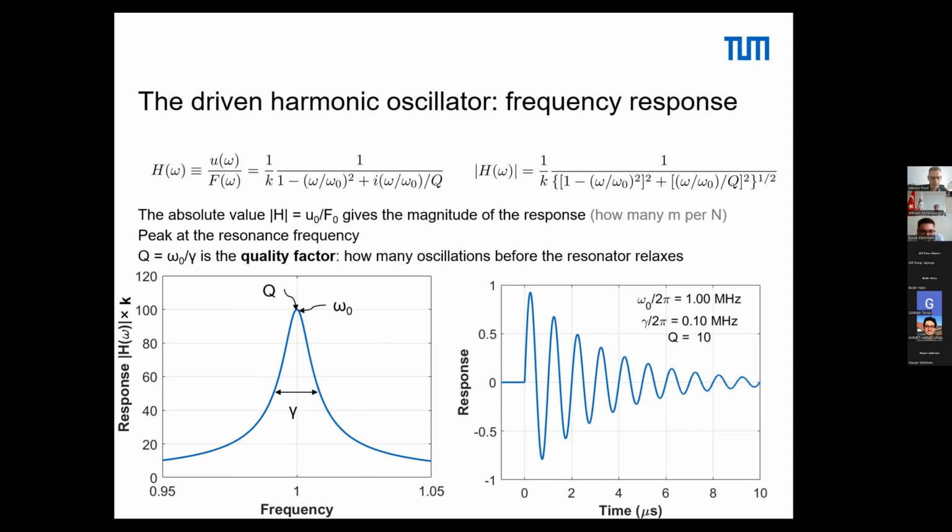So these defects on the surface are one contribution. There are in general many different types of contributions to the damping rate. And again, if we would have the full lecture, I could tell you more about two-level systems, Akhiezer damping, thermoelastic damping, clamping losses, and also air damping. But in view of time, we will not go there. Okay, I hope that has answered the question.